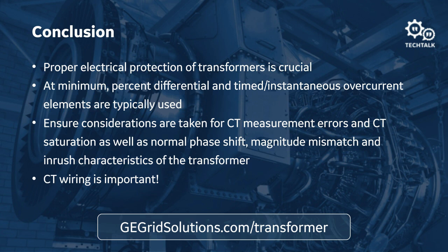Did you say that the relay can do DGA? DGA being dissolved gas analysis. The relay itself, the 845 particularly, does not do DGA itself, but GE does have some dissolved gas analysis devices. These are basically online monitoring devices that are mounted, tapped off of your transformer tank, and they monitor components within the oil. So it looks for different gases. It might look for moisture.